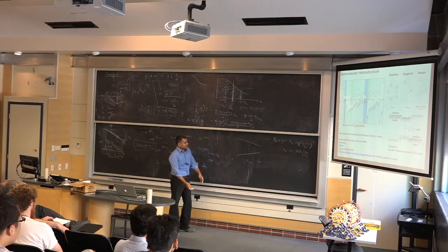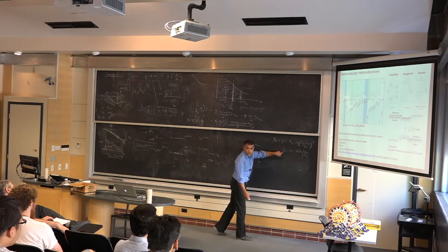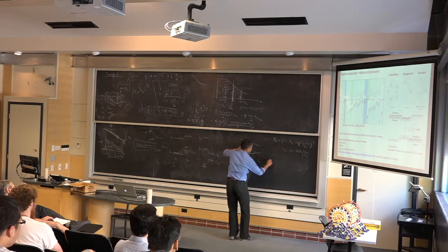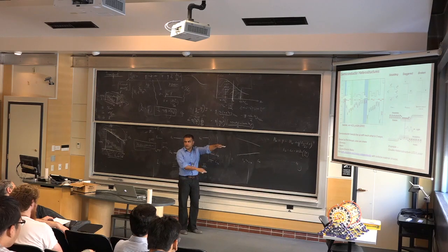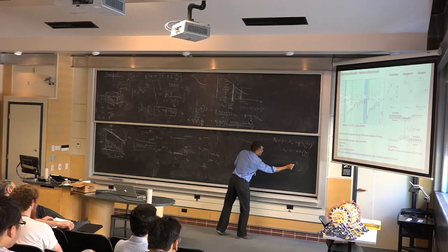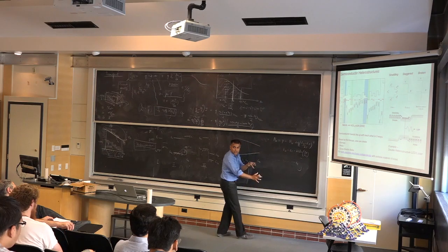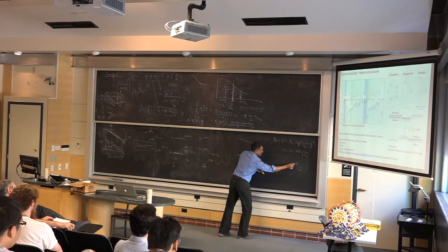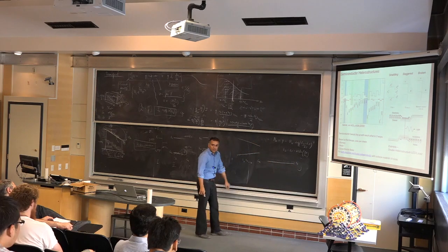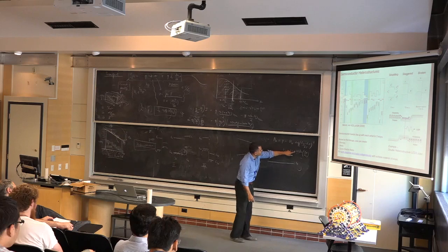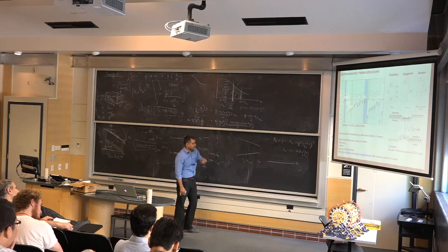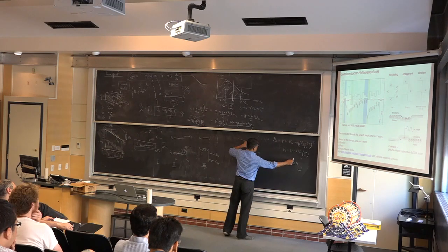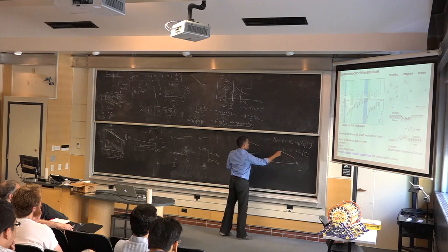So how far is your Fermi level from the valence band edge? You can draw the band diagram now. I've not done anything strange, I've not applied any electric field, so my Fermi level is always constant. The valence band will be this much distance away, so it will look relatively flat, though I'm not trying to draw it exactly. There'll be a slight change because NV is changing with space a little bit, but that's minor. It's a logarithmic correction, very small. But what you see is that all the change actually appears in the conduction band.